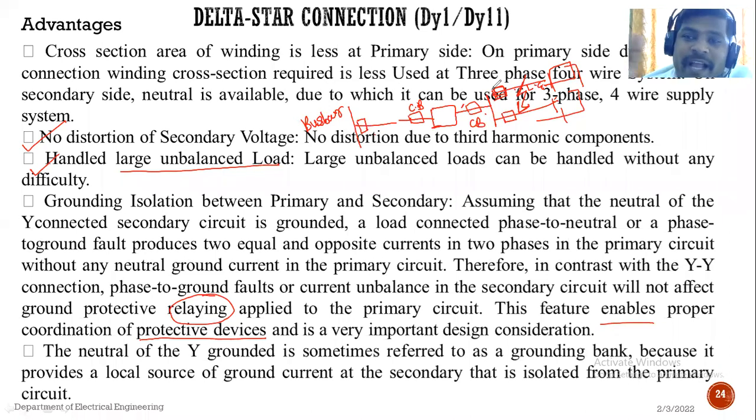then there is some backup protection also. There is always backup protection. Each and every equipment in the power system has a zone of protection, which can be divided into a primary zone and a secondary zone, and there are two types of protection. One is the primary protection, the second is the backup protection. If the primary protection fails to act, then to avoid damage to the equipment and apparatus in the power system, there is always backup protection.